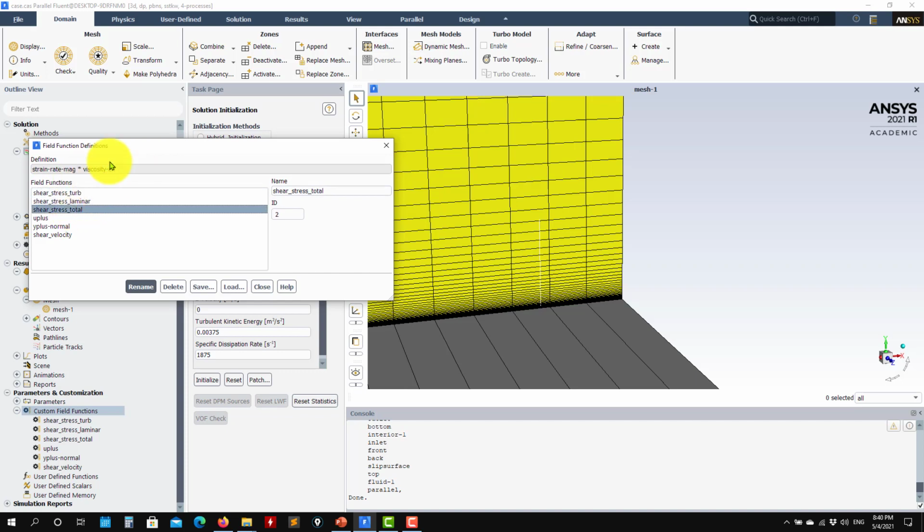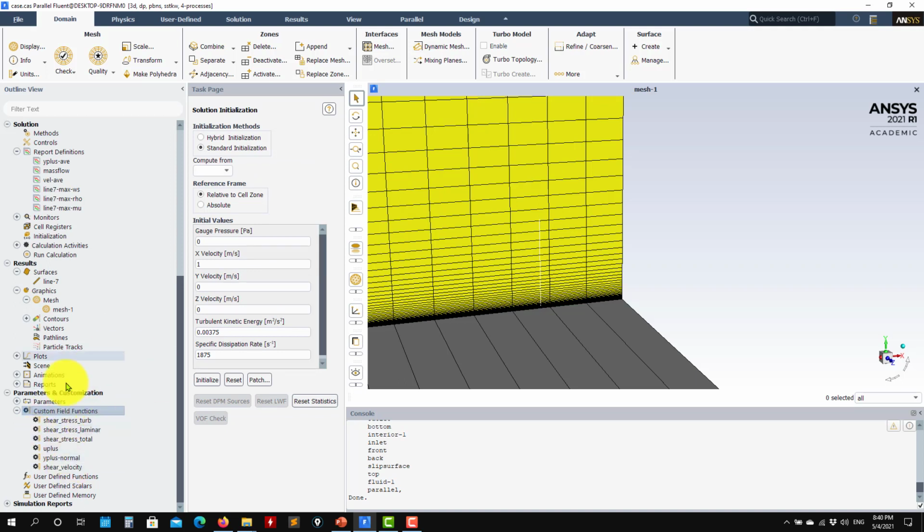So here, when we put the effective viscosity, it is laminar plus turbulent, but we can also create a new one. This plus this one is equivalent. So we compute this one and we can do the plot. We do all this because now we would like to do the classical plotting here, the loads, the wall, and everything. So when we run, I will show you that inside Fluent, but also how to save the files and do the plotting outside.